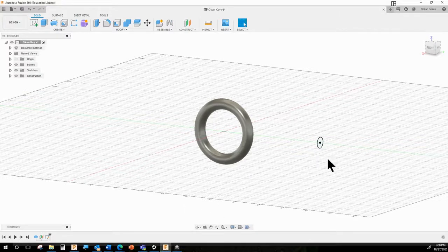Okay, so now we have this little circle floating in space, and we need to turn it into a little post that connects to the cylinder. And this is actually from a guy named Lars, who does these really great tutorials for Autodesk, but I do them a little quicker and a little briefer, and I think a little clearer. So the deal here is we want to extrude this out to the key, but there's some complexity to that that'll make you learn some new things about extruding.